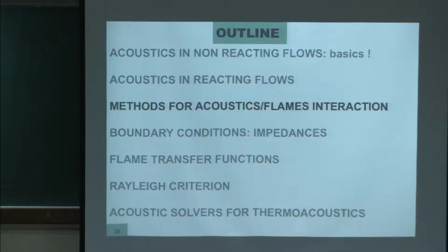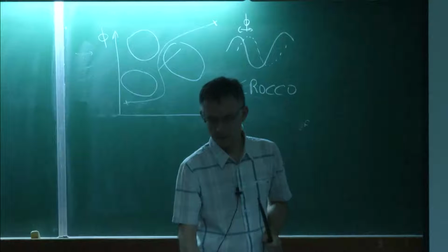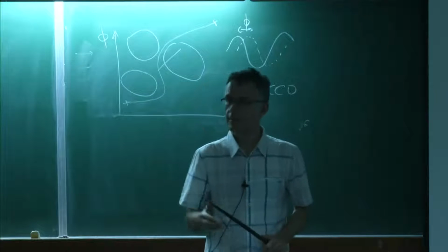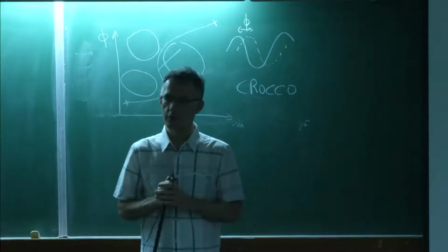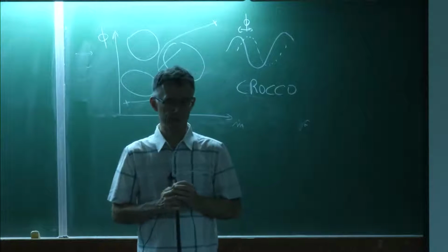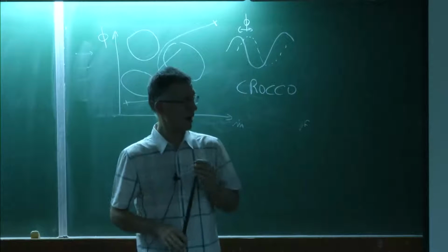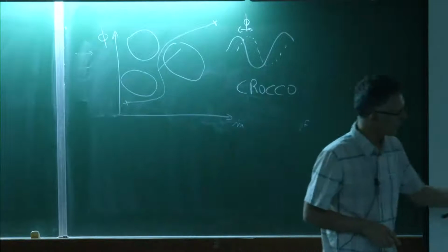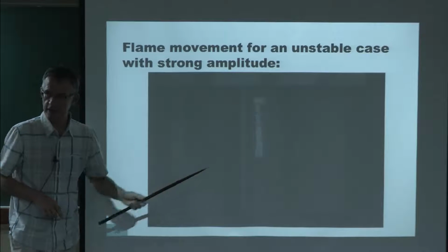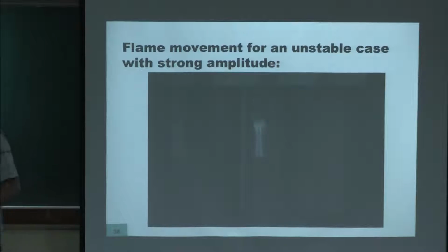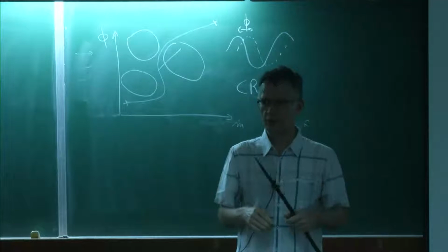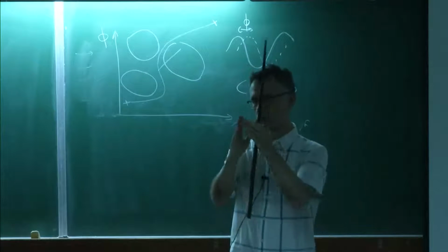So in the flame shape you're showing the cylindrical thing. We could have done experiments on M-type flames, N-type flames. Sure. What's the difference in the different modes? For swirl flames, yeah. For these flames, there's only one shape. It's always a V flame for that case. For swirl flames, yeah, sure, that's due to swirl. Swirl will make things much more complicated. So you can have M flames, V flames, all kinds of things. These flames are very simple cones.